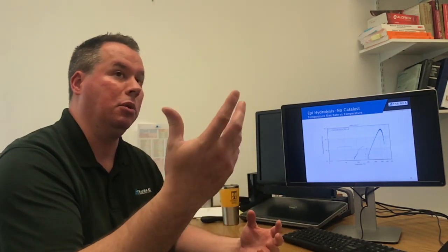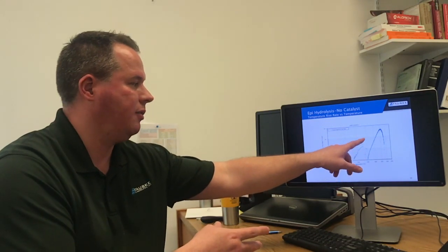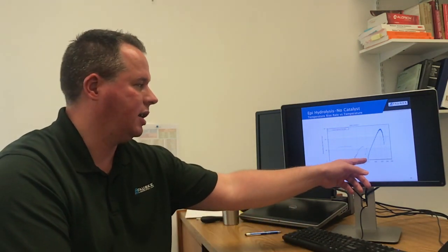So you really need to know the flow regime to know if it is going to be venting mostly vapor, leaving this liquid behind. Now you potentially have this other reaction to deal with in your reactor. Or is it truly homogeneous flow that is going to vent over to a catch tank, and now you potentially have to worry about this reaction occurring in your catch tank?